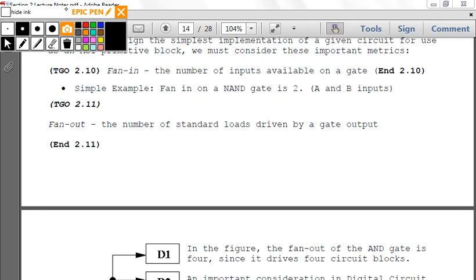If we haven't designed the signal strong enough, or we don't have a buffer that we can use to regain the signal, one of the things you can use buffers for is if you have a weak signal. This is a little outside the course, this is CMOS, but for you to know, if you design a buffer that's driven by the supply voltage and ground, you can use it to restore signals. So if you have a signal that's degraded, and it goes into the buffer, it'll come out properly. That's another reason you can use buffers.